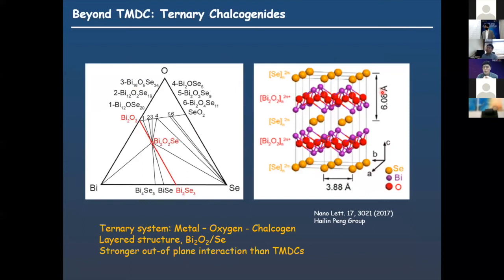As with all oxide materials, oxygen vacancies can generate a kind of electrical doping, so if there are many oxygen vacancies, it becomes quite a metallic material. So as you say, controlling the oxygen vacancy is important. But for now, with our optimal growth condition, we can generate a quite low level of oxygen vacancies, and then we can get a high performance transistor.